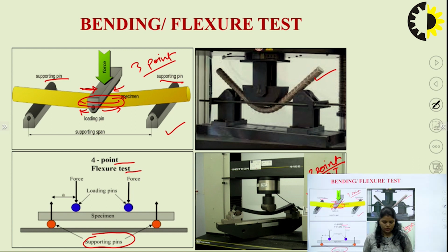ठीक है, अब shear stress को आप कैसे minimize करोगे, तो इसके लिए हमारे पास एक depth ratio होता है, and depth ratio is basically the length of the outer span divided by the height of the span. तो इनका ratio हम find out करते हैं, and then we can minimize this midline shear stress failure, premature failure. ओके, तो इसकी एक specific value होती है, अलग अलग material के लिए अलग अलग values होती हैं, तो इस value को हम control करके premature failure को avoid और minimize कर सकते हैं.